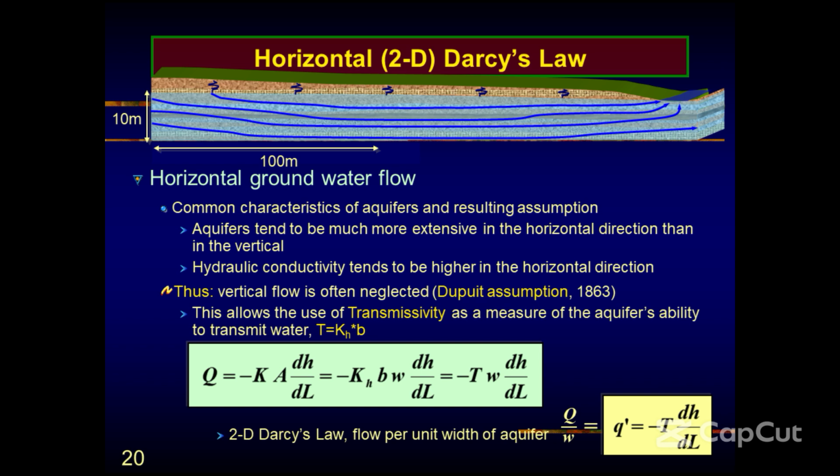So transmissivity is simply a function of x, y, which can be defined, let's say from 0 to b, of the hydraulic conductivity, which is x, y, z. We can consider all the components for the hydraulic conductivity, but the vertical flow, because this is hydraulic conductivity, not velocity. Are you following?